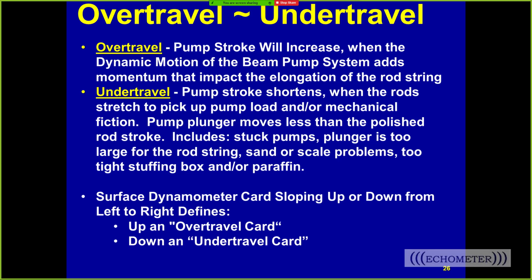Now, when you talk about a pump card that has over travel, it usually has too much over travel. Or a pump card that has under travel usually has too much under travel. But basically, the idea of under travel is a pump card that has lots of stretch, and an over travel card is one that has a pumping speed faster than zero, which is starting to get some additional pump stroke due to the inertia of the pumping system, causing the pump card to have a longer downhole stroke than just the stroke due to the surface stroke minus the stretch.